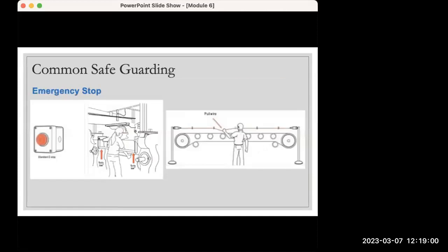Emergency stops. This is the involuntary tripping or activation of an emergency stop device if all or part of a worker's body approaches or enters the hazardous area or danger zone of machines. Examples include an e-stop button on a control button or near the worker or the danger zone, an emergency contact bar in front of the in-running feed rolls, or an emergency tripwire installed along a conveyor system.